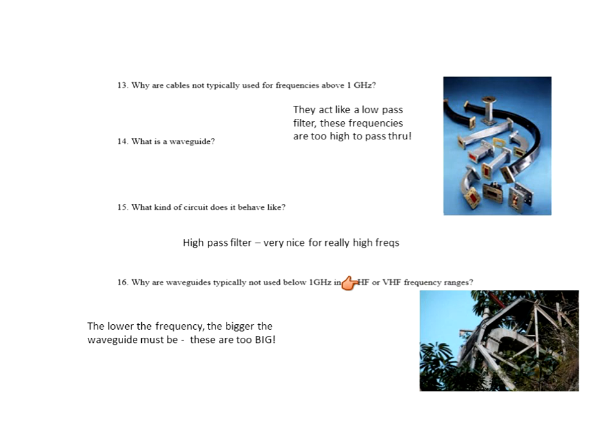Well, here's why. Looking here, this is an actual waveguide. It's a very, very large waveguide. It's got to be 4 or 5 feet across right here. I think this waveguide was taken at the largest satellite dish in the world, Arecibo in Puerto Rico. I've been there. But the lower the frequency that you use with the waveguide, the bigger the waveguide has to be. This is probably a 300 megahertz waveguide, I bet. It looks pretty large. It's around 300 megahertz.